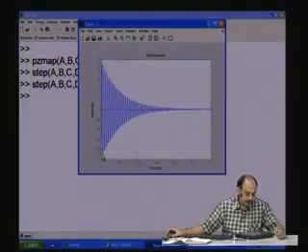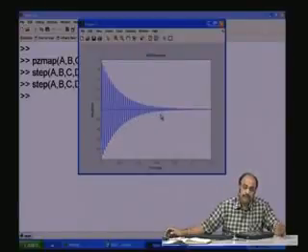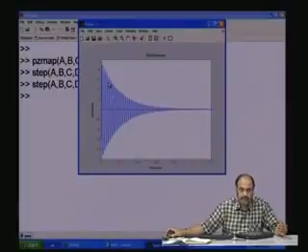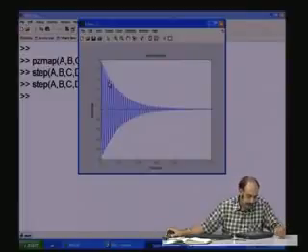And this damping is actually related to the position of the poles with respect to the j omega axis, how far it is from the j omega axis. And this oscillatory nature, as we were discussing, the frequency will depend upon how far it is from the real axis, that is, what is the projection on the omega axis.